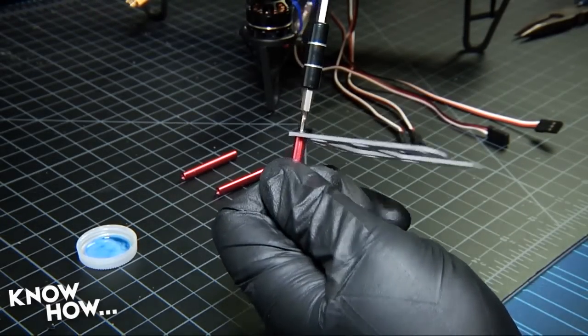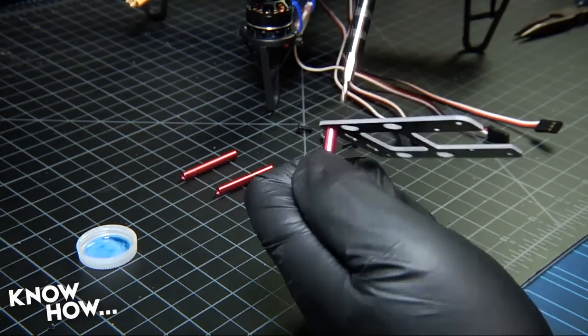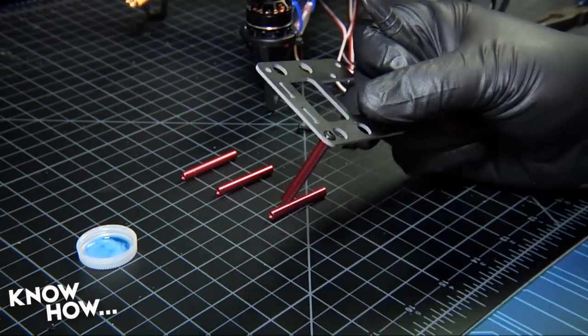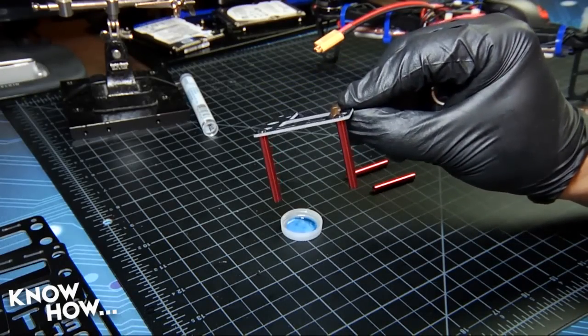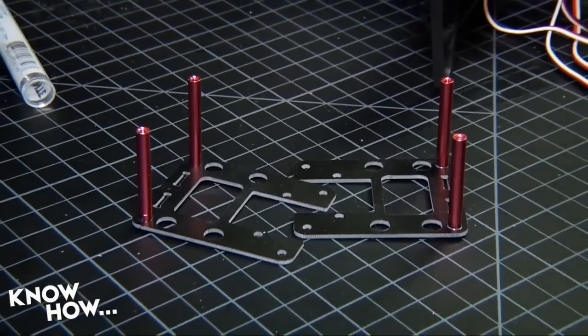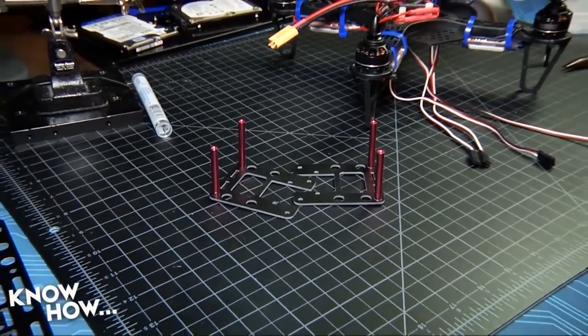This cage will give us the real estate we need to mount cameras, receivers, batteries, FPV transmitters, telemetry, and GPS receivers as we upgrade the KH250. The cage consists of 2 small plates, a large top plate, and 8 aluminum standoffs. Use the included screws to attach 2 aluminum standoffs to the edge of each of the small plates.